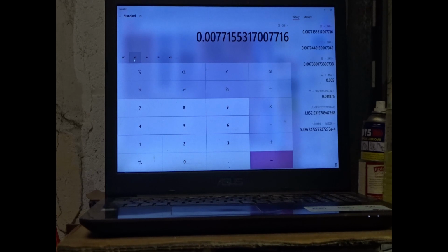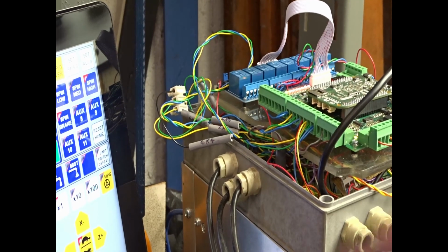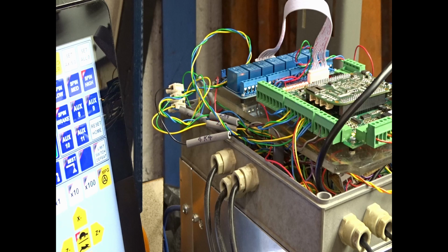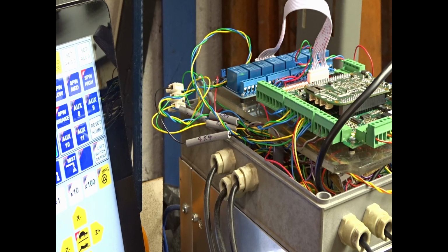We get 7.7 milliamps. So we're right down at the low end, but we're just about there. So I say all of those 6 resistors, I put them at 4K7 initially because I was concerned about damaging things, and I kind of figured start off high, but high is much too high.